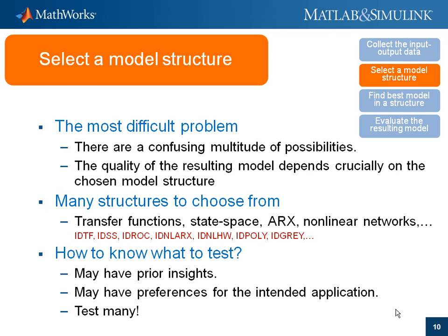So how do we know which model structures to test? It may be that we have prior physical knowledge, for example, that the system is known to be nonlinear. It may be that the intended model application requests a model of a particular kind. But in the typical case, we do not know really what to test. The basic advice is then to stick to a number of standard structures that can prove useful. One should be generous at this step and try many choices. After all, it is likely that you have spent quite some time and money on collecting the data, so spending a few seconds more to compute the model in a new structure seems like a quite reasonable effort.